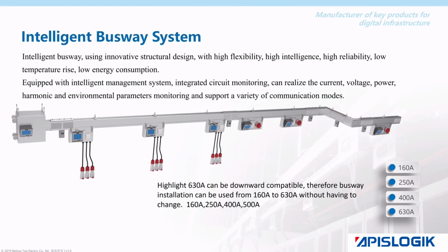Topline G busway is the most high-end series product we offer. It can provide flexible power distribution methods and is not affected by load changes. The products range from 160A to 630A, mainly composed of 5 parts: feeder unit, tap-off unit, housing section, L section, temperature monitor, connector, and related accessories, endover, installation accessory, etc., which can be flexibly assembled and configured for various computer room power distribution schemes.